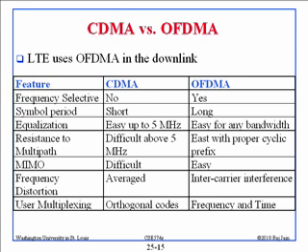All right. So CDMA versus OFDMA. I think we have discussed most of it, but I just want to repeat it one more time. If you want to be frequency selective, meaning there is a noise in this zone and you want to take care of it, it is much easier to do with OFDMA. It is not possible to do with CDMA, because if you have a 5 megahertz channel and you are using the whole 5 megahertz in CDMA, the frequency selective noise will affect you. So there is no solution.